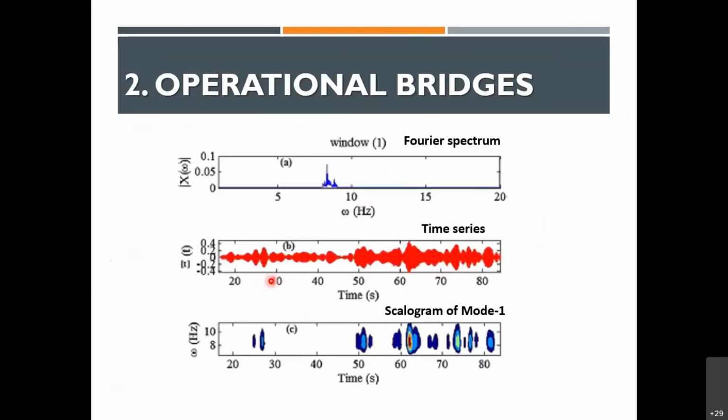Again, just by taking either something really simple like the Fourier spectrum of the harvested voltage value, or just taking a look at the time series or the scalogram of the various modes, we could start seeing, okay, if there were modes, we did some EMD as well, whether they were close by or not close by, and then compare it against our models.